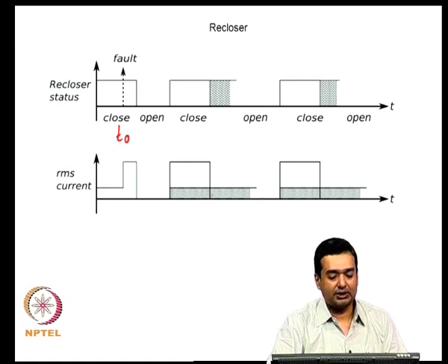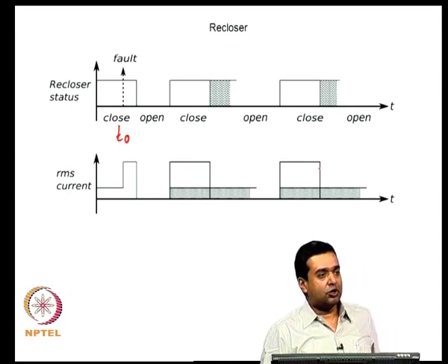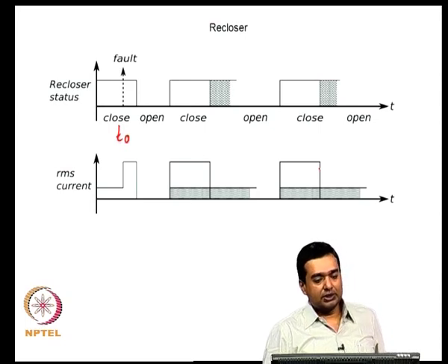So, the anticipation is now you have reclosed for a second time, you potentially have cleared the fault. So, you might go back to normal operation, or in case you have something really solid on the feeder causing a fault, then you go back to your high current level, you wait for some more duration, and then you lock out. So, at this point, if the fault is still continuing, your recloser will lock out and stop further reclose attempts. So, this is a recloser with 2 reclose cycles.